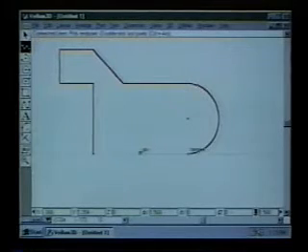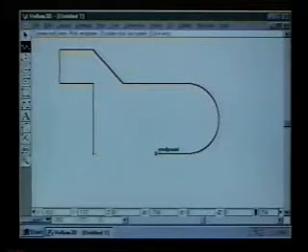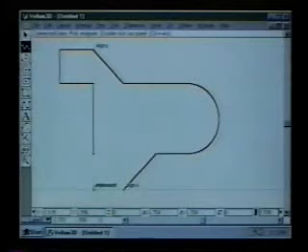Now I can slide across this, and now I'd like to draw a line that's horizontal across this area here, and I want it to end right below the midpoint of the line that's above. And initially I don't get any help from the drafting assistant, so what I'm going to do is go up for just a second, get on the line, slide across until it wakes up the midpoint, and then I just come down and it gives me an alignment off of that point, and there's the intersect that I wanted. So I can click there and draw my line. I can draw another line down here to this intersect, and I could slide across and hit that intersect.